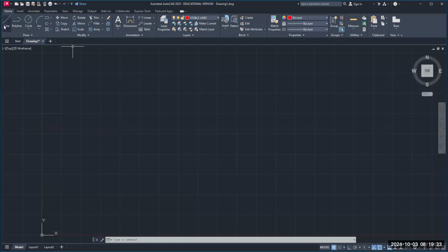All right, now come up here. We're going to go to line. We're going to use line and click about right here on the screen. Now, notice it's already red. Why? It's because we assigned a red color to that layer. Now, you remember the other day I told you there was a hotkey you could hit so that you make your lines perfectly horizontal or perfectly vertical. Okay, so hit the F8 button. Look what happens. Isn't that beautiful? Makes nice, beautiful straight lines.